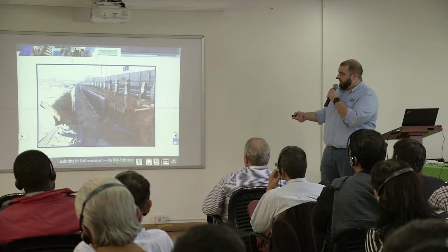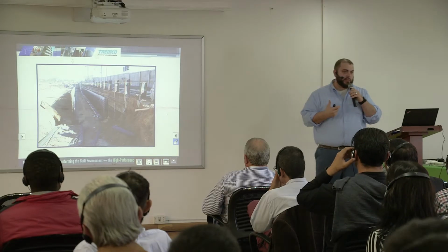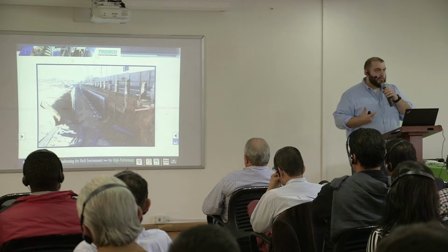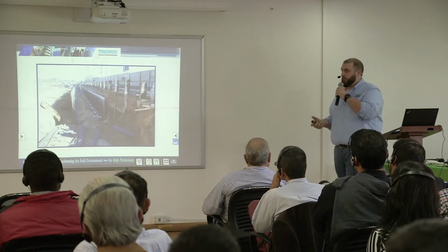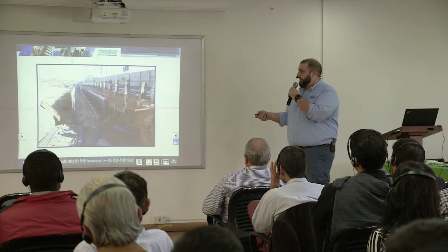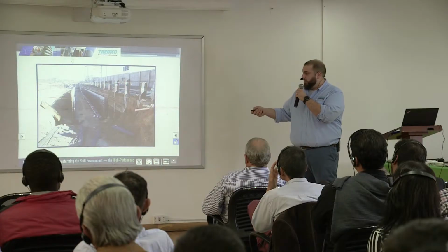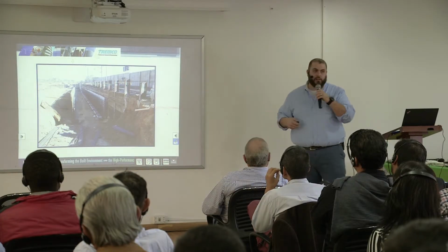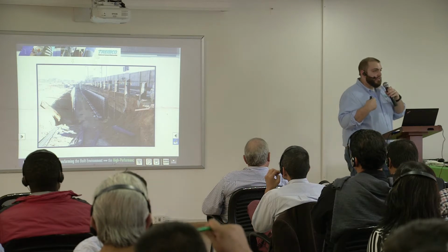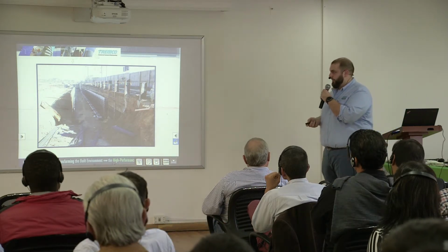It's hard to see with the light, but the concrete wall is not in yet. But you can see that clay, that lighter material, that is the bentonite from the Paraseal product that we'll talk about this afternoon. And you can see that behind that, hanging out over there, is the drainage. What they'll do is they'll put a form over here, and then they will pour the concrete in there, and then they get that compressive strength of the concrete to the bentonite, which provides your secondary waterproofing system there.